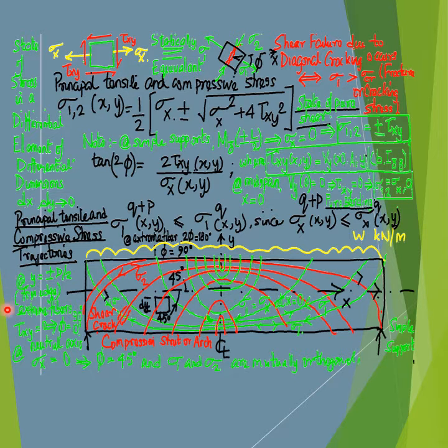As well as the extreme fibers, that is at the y coordinate equal to plus minus d by 2, that are the free edges of the pre-stressed concrete beam, at which the shear stresses are 0, while the normal or direct bending stresses are maximum in their absolute value.